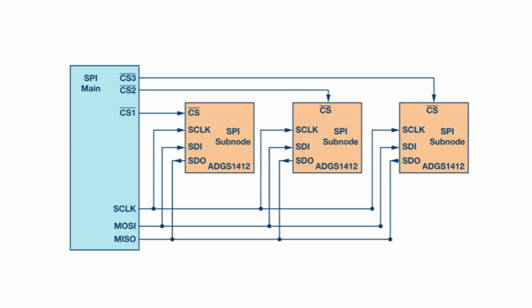Always make sure only one CS is low at any given time. Ensure slaves correctly tri-state their MISO line when deselected. This is vital to prevent bus contention, where multiple devices try to drive MISO simultaneously. Sometimes pull-ups on the CS lines add robustness, and definitely use software NSS mode on the microcontroller so you have full manual control over those CS pins.